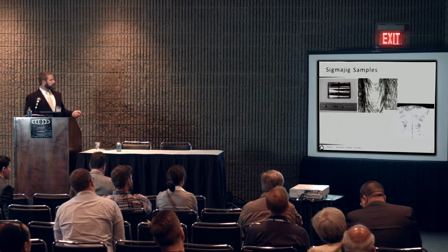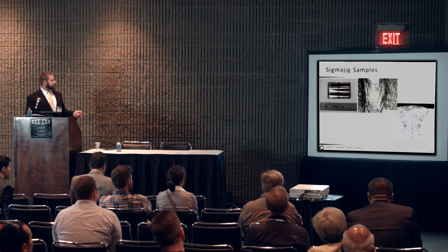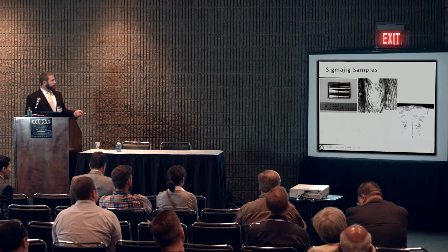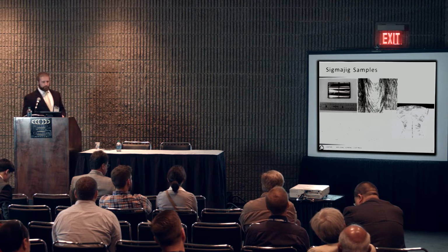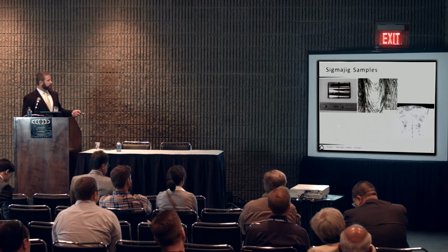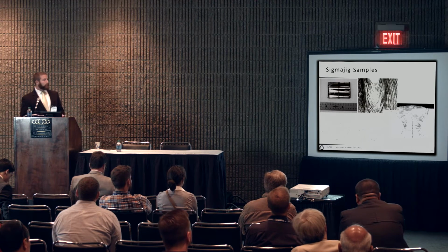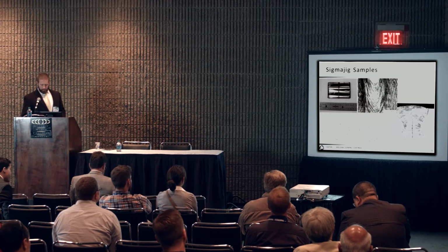So the three sections that were taken to look at the subsurface cracking are indicated in these faces here. They're always at the end of the weld where your highest tensile stresses are generated. It's been shown that sometimes at the initial portion of the weld, you typically have compressive stresses actually on the solidifying weld pool.